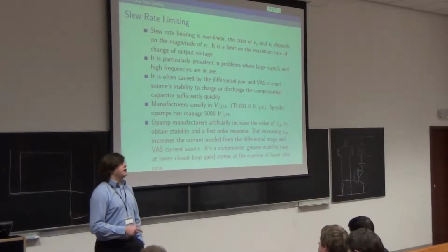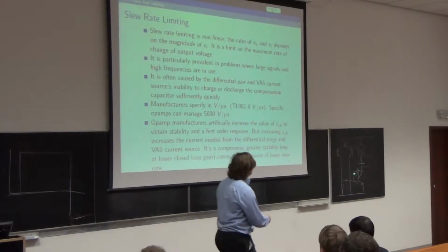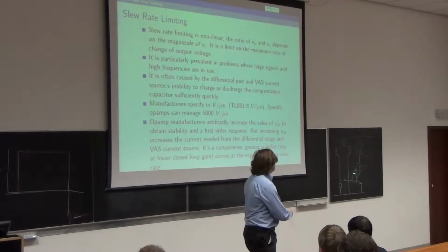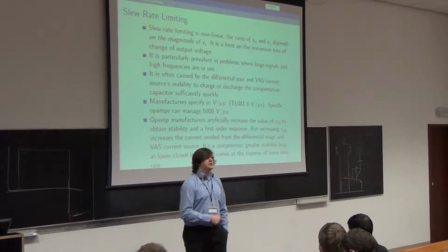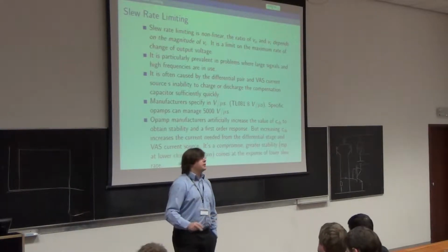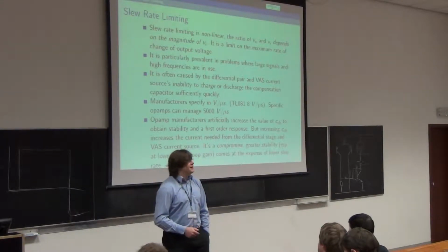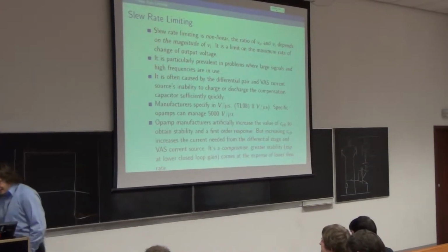Secretly, CCB varies because the depletion capacitance varies, because the amount of reverse bias of this junction varies. So making my additional bit much bigger than the CCB that's already there is desirable because it stops this variation being very important. But you don't have to worry about that. It's just something that I'd like you to know, but I've got to stop somewhere. Otherwise they'll tell me off.